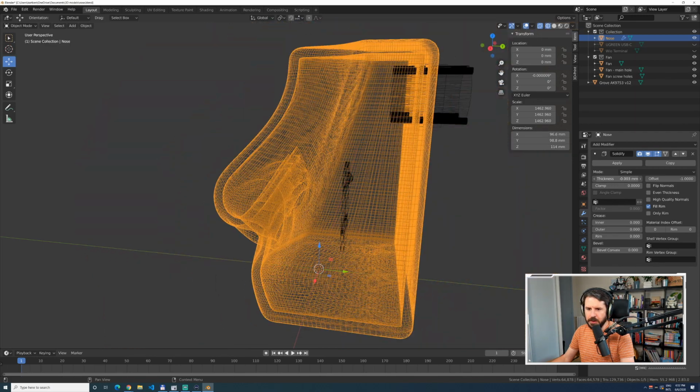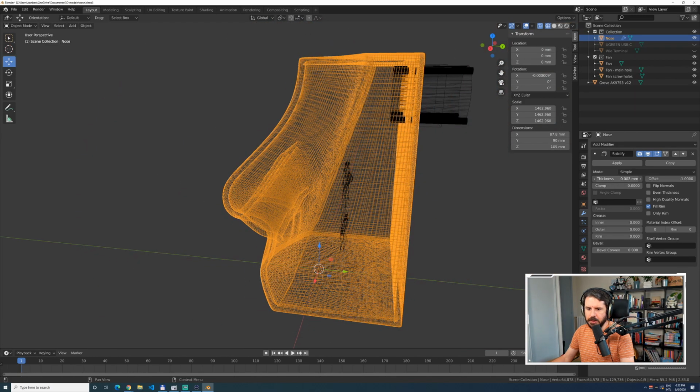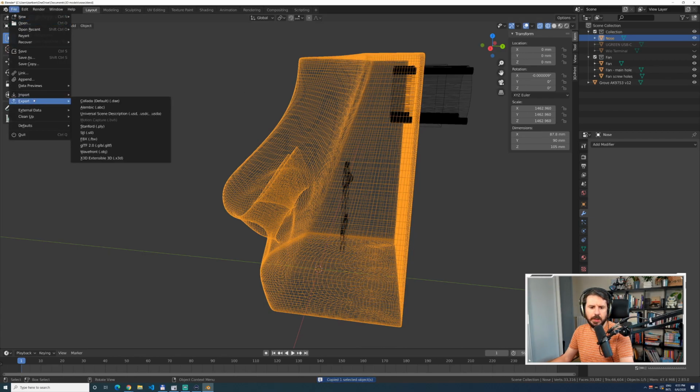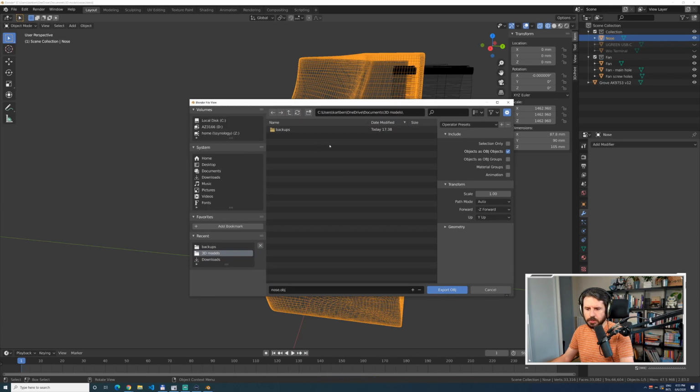and have something like this, right? Like creating a shell, so that instead of being a solid, this is indeed more like an actual enclosure, and then I can work on making it so as I can open it, etc., etc. But again, that won't work because it's not accurate enough, and it won't give me a nice smooth shell. So what I'm going to do is take this object and export it so as I can use another tool called Mesh Mixer to create a shell.